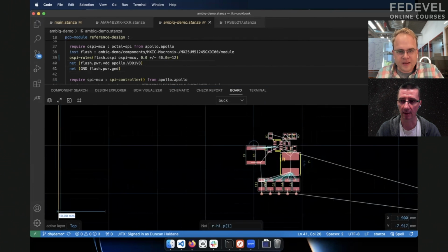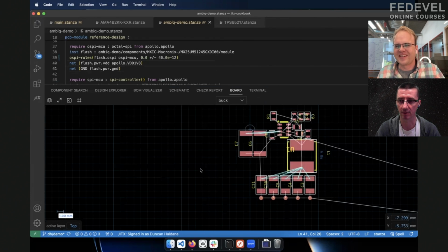And so this is kind of, you can also make it parametric placement, right? Based on the code. Okay. Yeah, so you can also make it parametric. You notice that these caps, the number scales as you adjust the ripple voltage, and you can script that in too. So it's not just a static thing. I've got parametric structures on my board, and I know how to put them down. Dragging them around in the layout tool is not interesting. There's not going to be a "oh, I found a new optimal layout for this." No, you just reuse it.